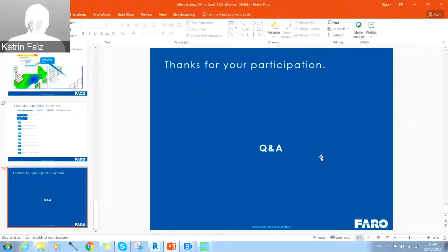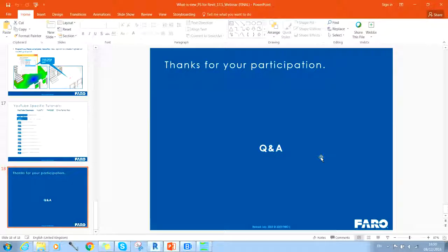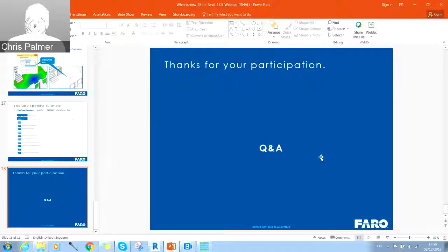Okay. I think Chris just wrote another comment. The insulation on pipe fittings, especially larger pipe fittings, the outside diameter or shape around the fitting is far different than the actual diameter or shape of the fitting. There's not really a lot that you could do about that, to be honest with you, because we can't see through the insulation. Unfortunately, we can only model what we've got visible, because obviously laser scans are line of sight, and that is literally just a limitation of laser scanning.